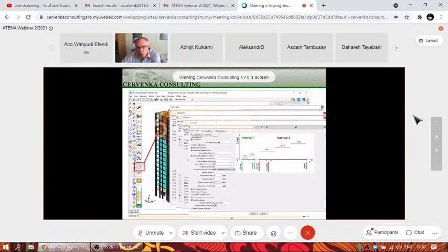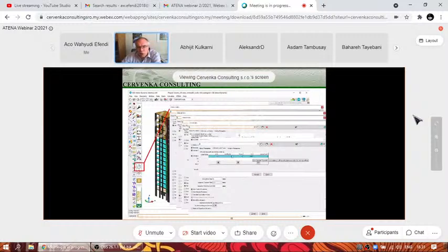In addition, I want to mention one option for the users who are using ATENA. Sometimes they don't know about this option, but you see there is this additional load cases tab when you define interval data, which can be used to reuse some of the load cases or some of the boundary conditions from a previous interval.